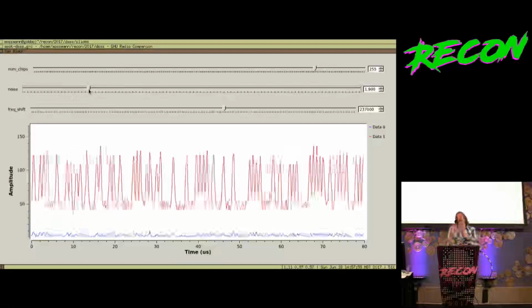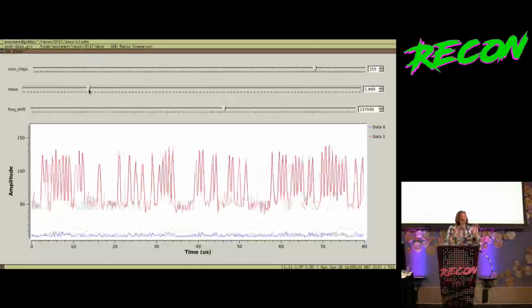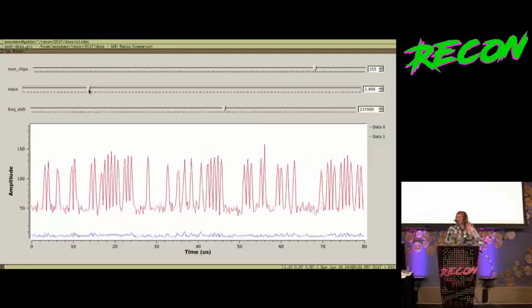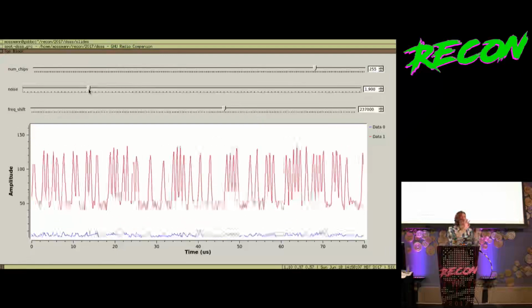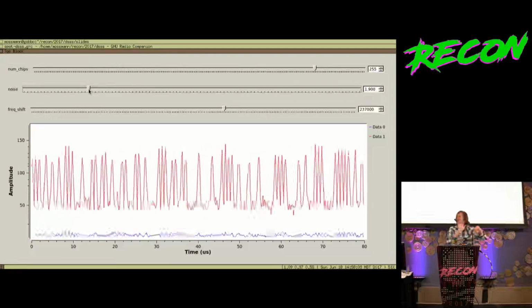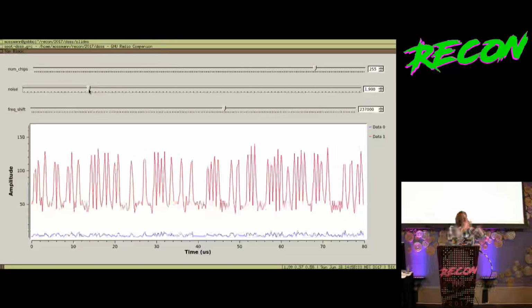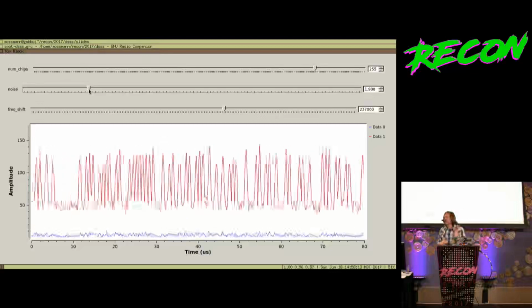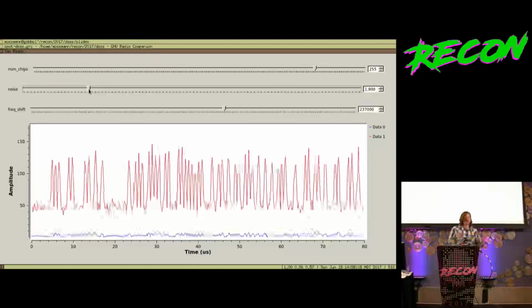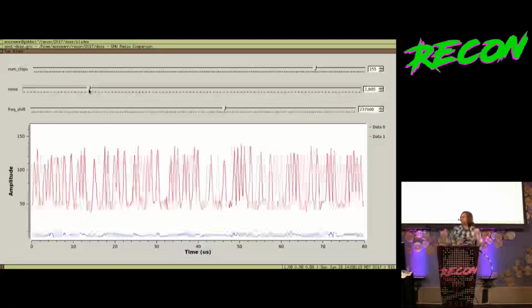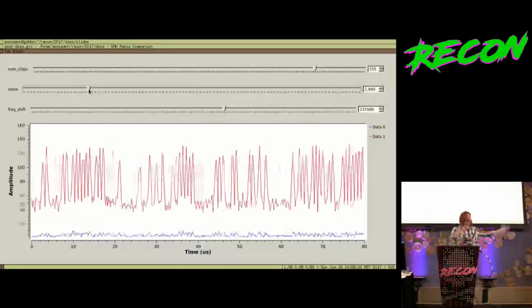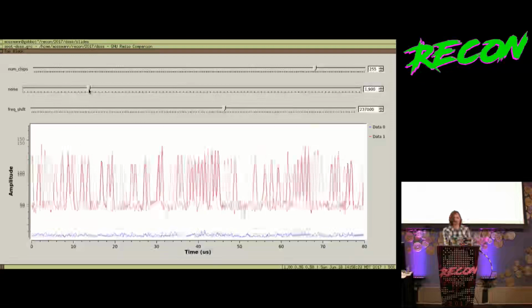And it doesn't matter if these chip sequences are inverted or not. Some of these chip sequences are representing a 1, and some are representing a 0, so their entire sequence is inverted. But since I'm doing the differential, the chip differential is the same regardless of whether a 1 was transmitted or a 0 was transmitted. And so they stack up together because I'm doing the differential.